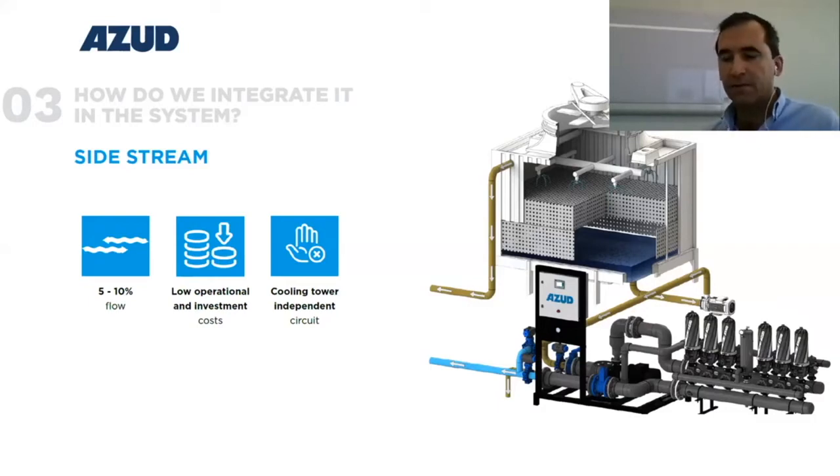These systems remove suspended solids, organics, and silt particles for a portion of the water system on a continuous basis, reducing the likelihood of fouling and biogrowth, which helps to control other issues in the system such as scaling and corrosion. This improves the system efficiency and often reduces the amount of water blowdown. So you will also have a lower environmental impact.